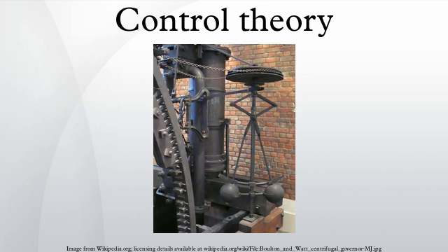The state space representation provides a convenient and compact way to model and analyze systems with multiple inputs and outputs. With p inputs and q outputs, we would otherwise have to write down q times p Laplace transforms to encode all the information about a system. Unlike the frequency domain approach, the use of the state space representation is not limited to systems with linear components and zero initial conditions. State space refers to the space whose axes are the state variables. The state of the system can be represented as a vector within that space.